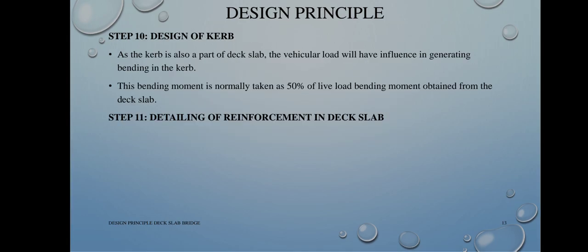Step 10 is the design of curb. As the curb is also a part of the deck slab, the vehicular load will have influence in generating bending in the curb. This bending moment is normally taken as 50% of the live load bending moment obtained for the deck slab. Step 11 is the detailing of the reinforcement in deck slab.